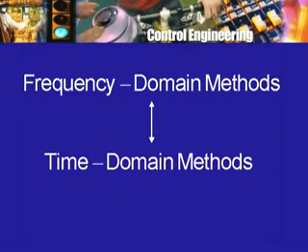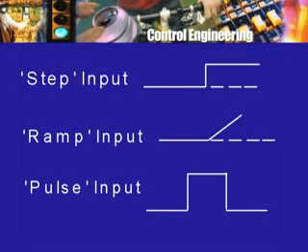In particular, response to inputs like step input, one talks about the step response, response to a ramp input or response to a pulse, very often what is called a rectangular pulse, a single pulse of this kind, or a response to a square wave input and the like. Now, a step input of course has nothing to do with periodicity. It is just a signal which starts at some time and then keeps on being at a particular level for all time to come. A pulse appears only for a short time and then it is 0. It is really a transient input.